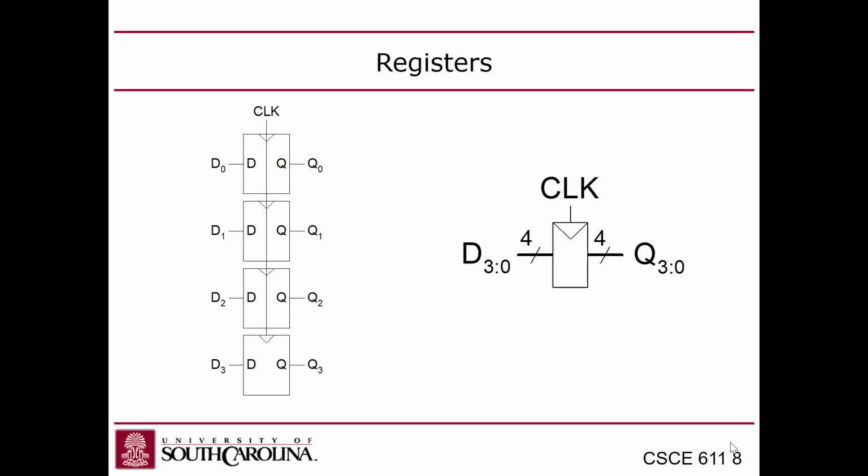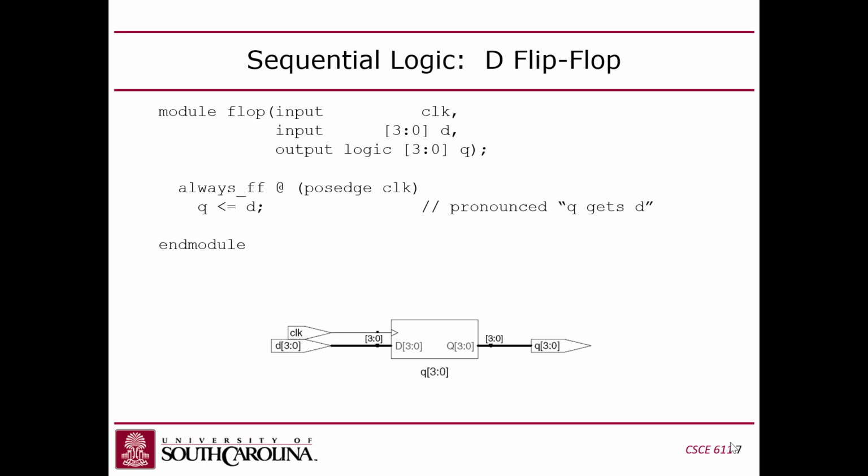Question? Basically, anywhere where we would see a multi-bit flip-flop, the term is just register. Register, yeah. We don't call them flip-flops. I don't know why. So just contextually, then, we'll know when we're dealing with the MIPS stuff, register in context of the register file. We'll just have to look and see. Right. Yeah. This is an example of it. So this is a 4-bit register, but it's not the same as a MIPS register that has an address. A MIPS register is part of the instruction set, and this is just any bytes. Yeah, the difference is what level you're at. If you're at the microarchitectural level, then that's a register. If you're at the instruction set architecture level, then a register is a numbered location in the register file.